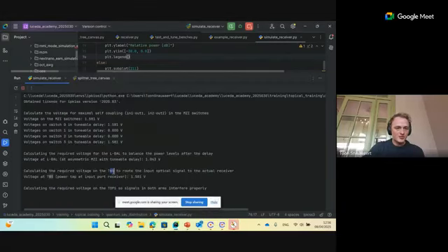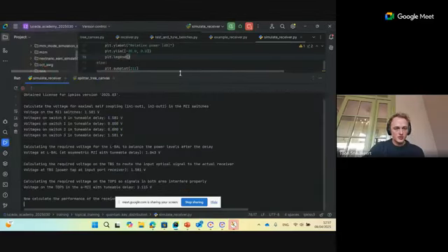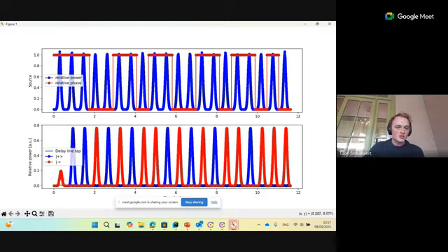Then for the tunable beam splitter, and for the TOPS shifter. And once we have all our bias voltages, we are able to run our complete test bench and have a look at the output response of our two outputs at the directional coupler.